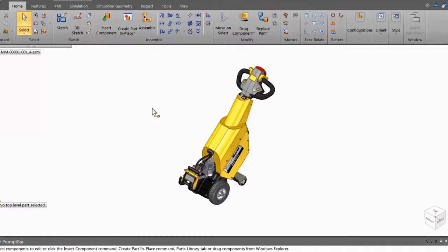Top-down assembly modeling is an assembly-centric method which starts at the highest level possible with individual parts and sub-assemblies defined within the context of the overall assembly. To help you with planning top-down assemblies and make building assemblies faster and easier, Solid Edge provides a suite of commands and tools like virtual components, copy sketch, assembly-based features, assembly sketches, and finally, the most versatile feature, create in place. In this video, we'll show you how it works.